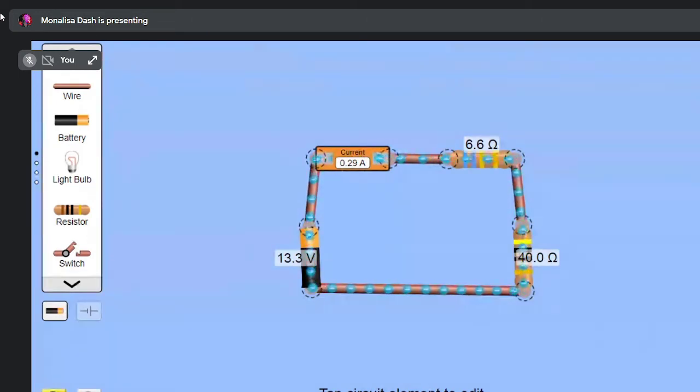So there are 4 circuits. First is your complex circuit. Then you determine the VTH, that is the VTH circuit. In the VTH circuit, you have to open the load resistance and measure the voltage by the voltmeter. Then you go to the RTH circuit. In the RTH circuit, you have to short circuit both source voltages, take a battery and an ammeter connecting there and measure the resistance. And last, the equivalent circuit.